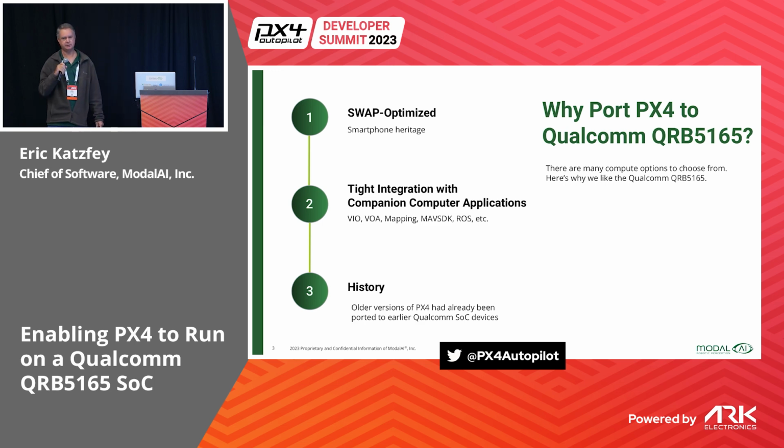Point 2 here, there was actually a comment after one of the keynotes about tighter integration between ROS and PX4. And that's one of the great things about putting this all together on one device: now PX4 and ROS and whatever other kinds of applications you're going to run on there, computer vision, machine learning, AI, that can all now be much more tightly coupled. You're not just going through a serial port and sending MAVLink messages back and forth. You can do more complete integrations and higher bandwidth. So that's